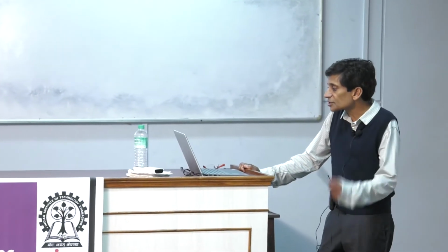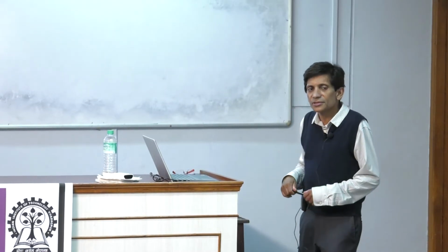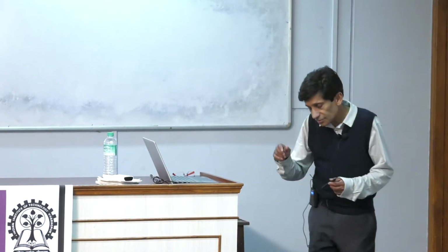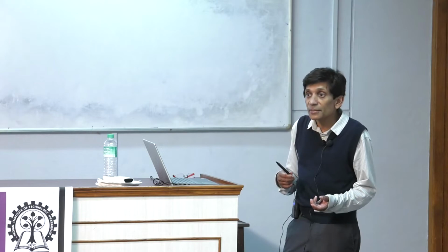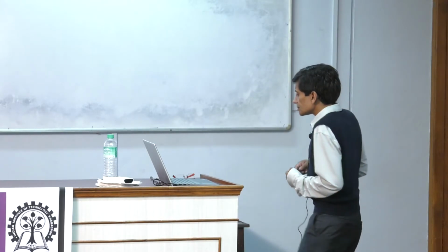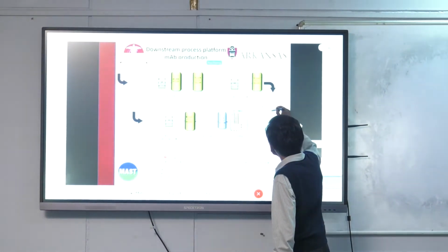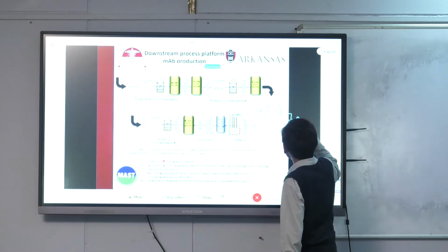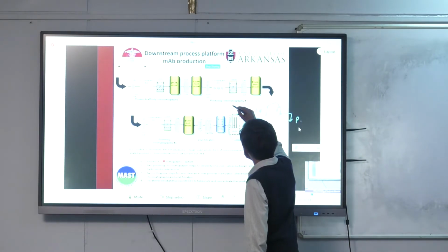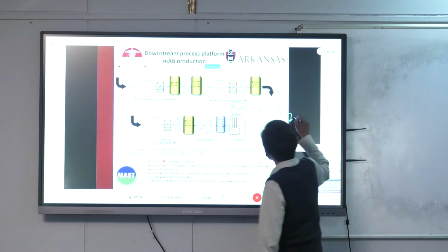So in terms of future directions for this sort of work, and we'll talk about this hopefully on Thursday, single-use devices. I mentioned that for microfiltration, also tangential flow microfiltration, also tangential flow ultrafiltration, they're single-use devices. Continuous biomanufacturing: in some ways, we said this is continuous, but in some ways it's not really, right? Because here's your feed tank. Here is your module. Here is the permeate you're collecting. And then here is your diluent or buffer tank, if you're doing a diafiltration. And so you're continually adding this, taking this out.